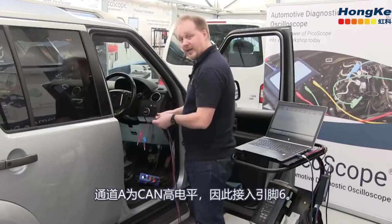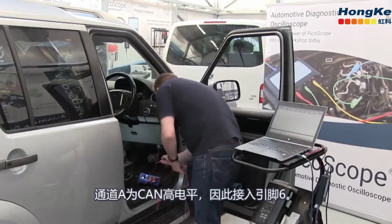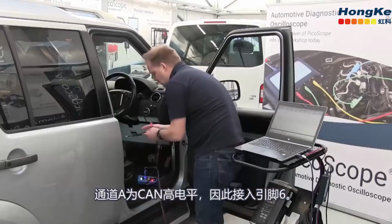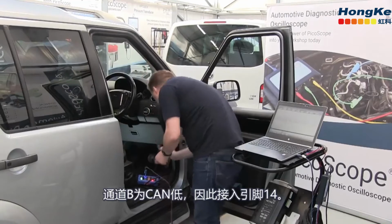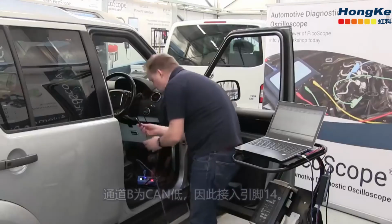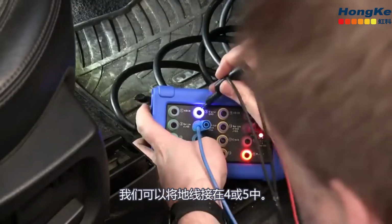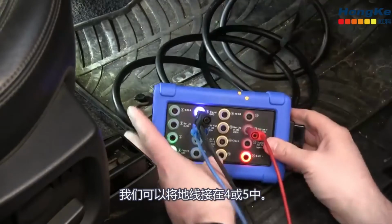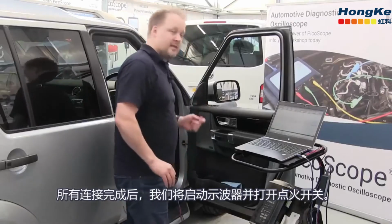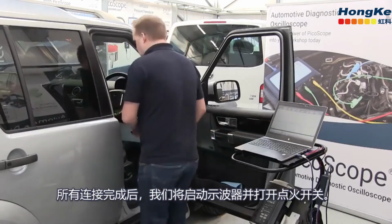Channel A, if you remember, is CAN high, so that goes in pin 6. Channel B is CAN low, so that goes in 14. And we can put our earth fly leads in either ground, 4 or 5, equally okay. So that's all connected. Again, we'll start the scope and we'll turn on the ignition.